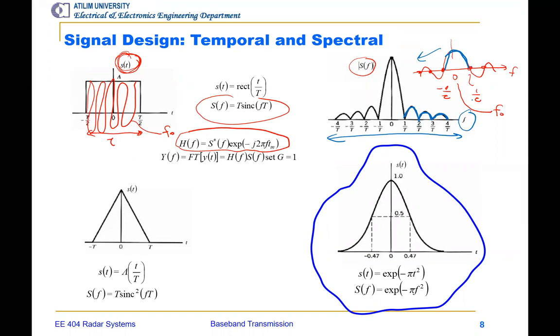It's mostly called pulse shaping. So one way to reduce the power in this side lobes is to shape this rectangular pulse. So instead of a pure brick wall type rectangular pulse, we can smooth it just like this, okay?